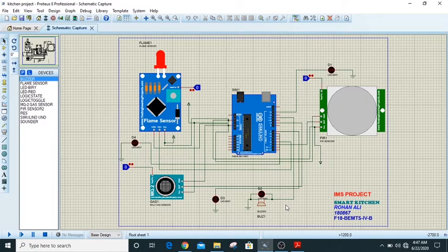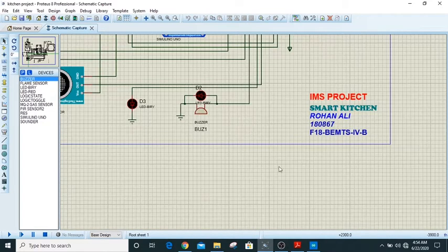Similarly, when there is smoke or a gas leakage, the MQ2 gas sensor gives a digital input to the Arduino, and the Arduino starts the fan and also gives a warning alarm along with a flashing LED. Similarly, when there is fire inside the room, the IR flame sensor gives a digital input to the Arduino, and the Arduino initiates the warning alarm along with the flashing LED. Now let's move to the Arduino code which drives our circuit.